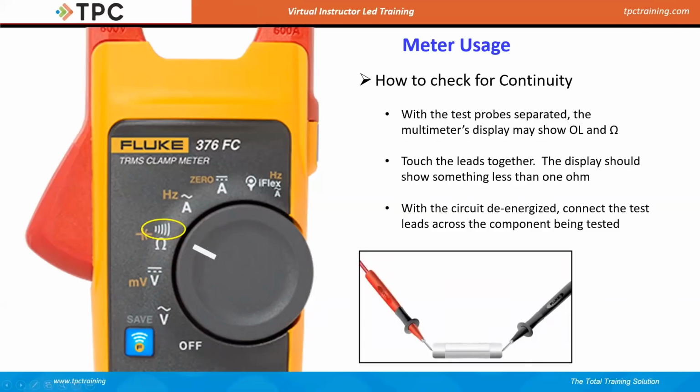So, okay. Now we test a fuse like this right here. We would expect to see something close to 0 on a good fuse, 0 ohms, less than 1. That's a good way to think about it, less than 1 ohm. And if it's a bad fuse, it would be open and you would see OL for a blown fuse there. So let's see if we can't put this to use.